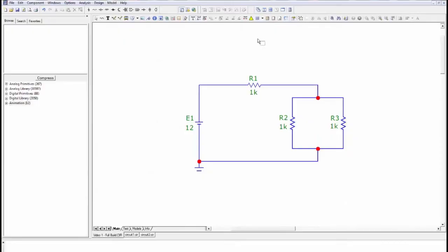One of the very useful tools on this simulator is this thing here. It's called rubber banding. Now at the moment that looks like it's turned off, so if I was to change this component, say I made an error and I want to remove it, because rubber banding is off, I can just lift the component out of the circuit and hit the del key if you want to, and it disappears, and then replace it with something else. Let me do Control Z, bring it back to the way it was before.